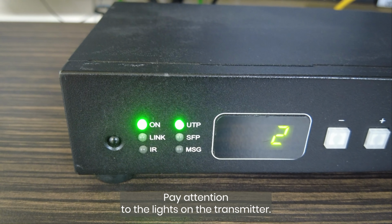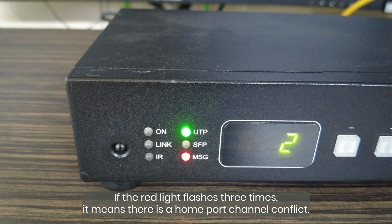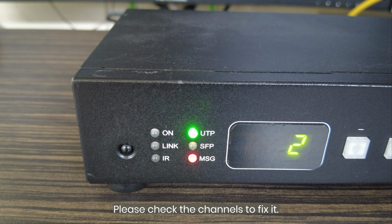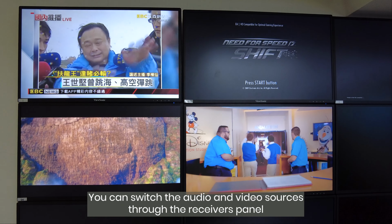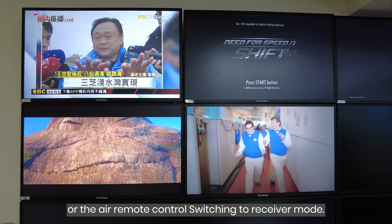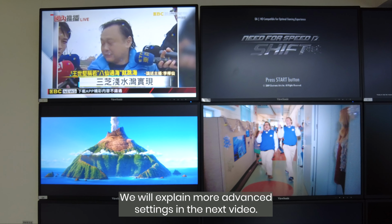Pay attention to the lights on the transmitter. If the red light flashes 3 times, it means there is a COM port channel conflict. Please check the channels to fix it. You can switch the audio and video sources through the receiver's panel or the IR remote control, switching to receiver mode. We will explain more advanced settings in the next video.